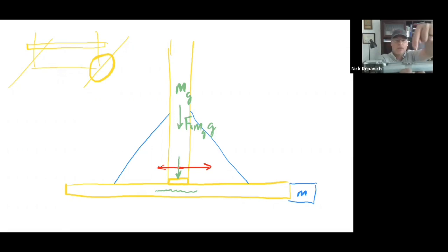So you actually go look up and say, okay, how much can this bearing handle in this direction? It'll give you 3 different loads. In this case, well, actually 2. It'll give you side load, which is if you have the bearing mounted this way, then it might see a side load. If you have the bearing mounted this way, it's going to see a direct top load. Then you would go look to the manufacturer specs, see what they call it, and compare and see if this holds the load.